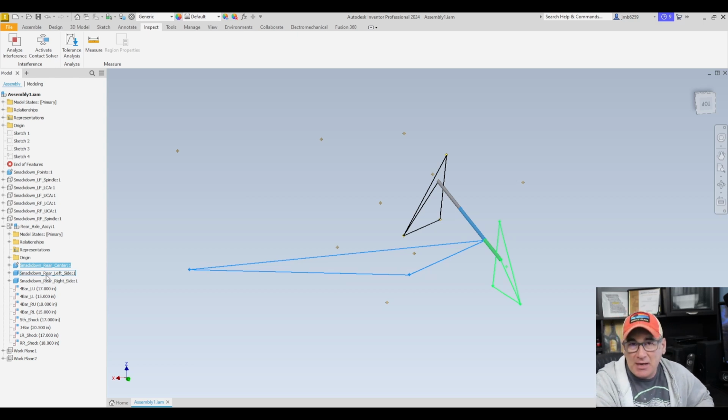Now, one thing I want to point out is in these birdcage bodies, you saw in those pictures where that axle tube goes through the bearing assembly. In our mathematical model, even though obviously it isn't like this in the real world, I want you to think about if we were to slice that axle into 3 different sections: a center section of that axle tube that goes with the center axle housing, a section that goes with the left birdcage assembly, and the other part going with the right birdcage assembly.